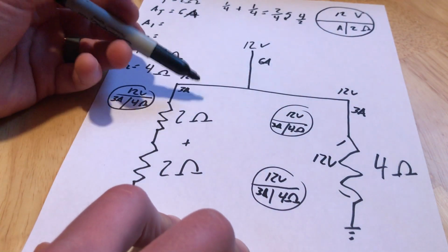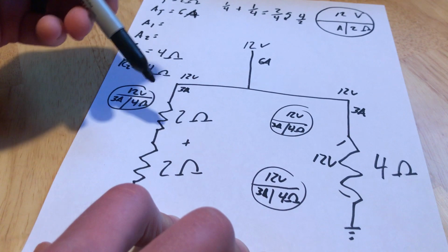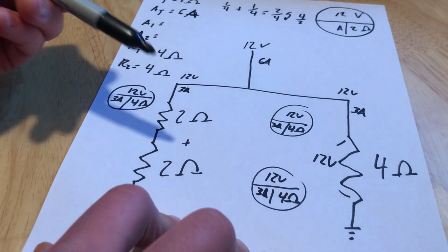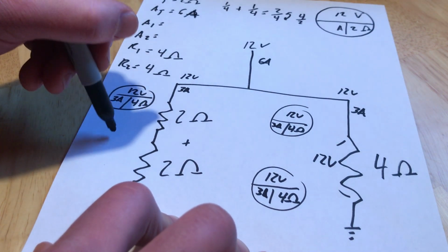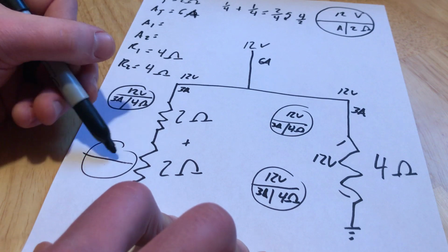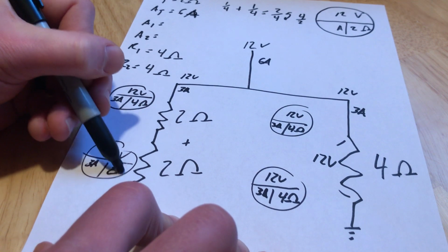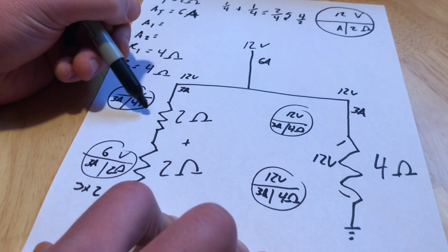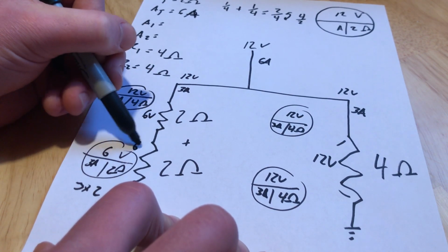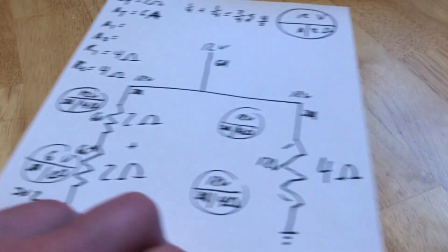And then over here, we should start to be seeing that I'm going to drop half and half of the voltage because I have two resistances and they're both the same. So each one, since there's only two, is going to drop half. But we can prove that too again. Solving for voltage. Got 3 amps. I've got 2 ohms. 3 times 2 equals 6 all day, every day. Alright. Throws that up to 12. So there's our completed circuit math for this one.